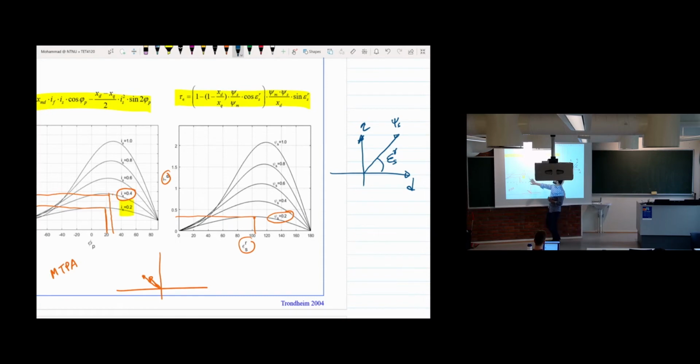So one way to represent the torque is like this, and the second way is to represent the torque in terms of the stator flux equation. If we keep the stator flux constant, then only the position gives us the maximum torque. It tells us how we can get the maximum torque for the same flux with a different angle. If we set the angle somewhere here, it gives us the maximum torque at this point for this amount of stator flux. Based on this knowledge, we can develop the control for the PMSM machine.